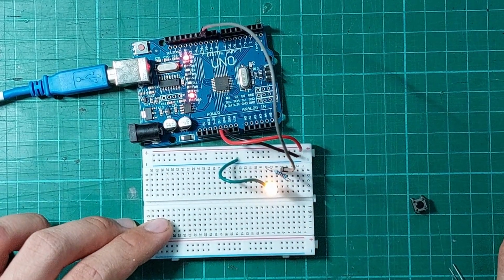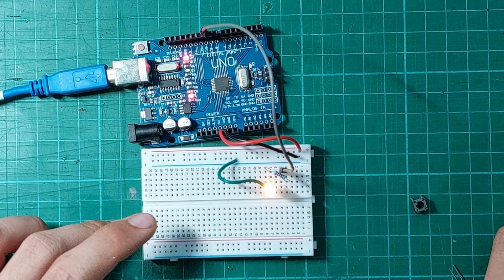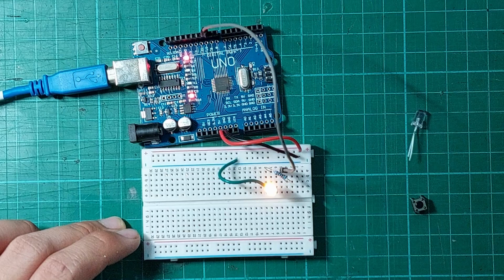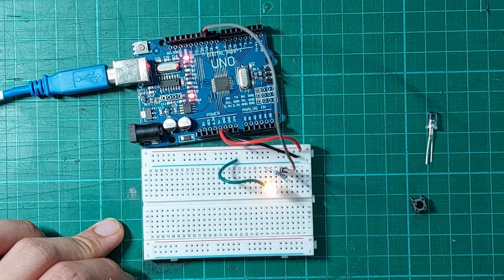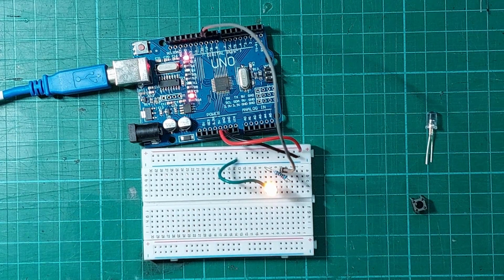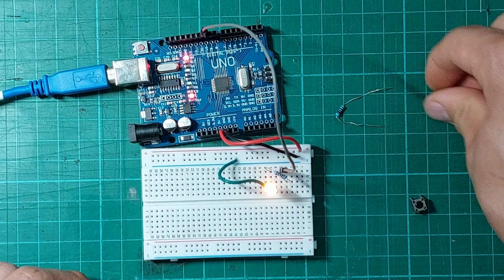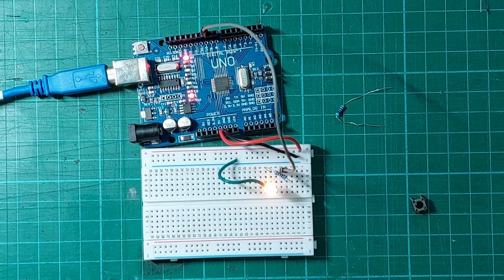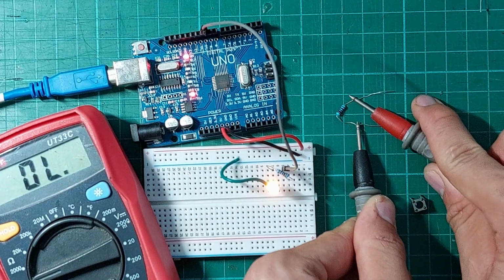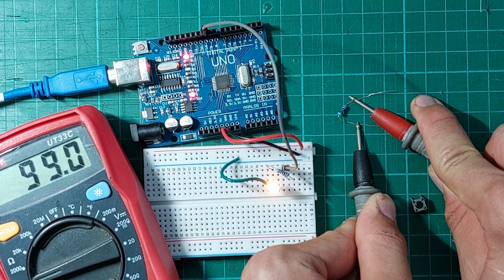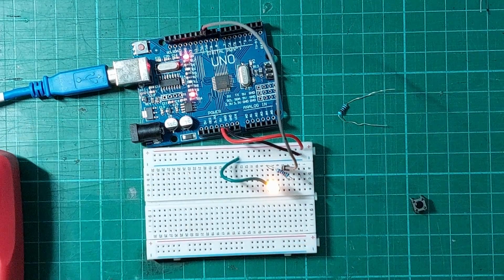How are we going to tell if it's actually half the brightness? Well, we got another LED. Now let's put that on. So I'm going to get myself another 100 ohm resistor. Once again, for the sake of our LED, I'm going to measure its actual resistance. We can never take the value that is in the box too seriously because we never know when they mess up. Okay, so 99, that's approximately 100. Good, we can take that.